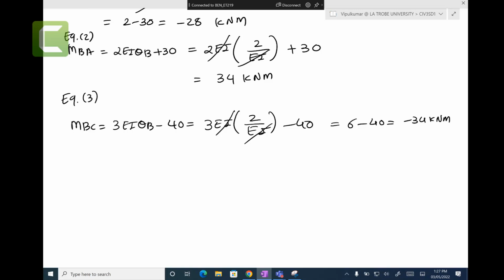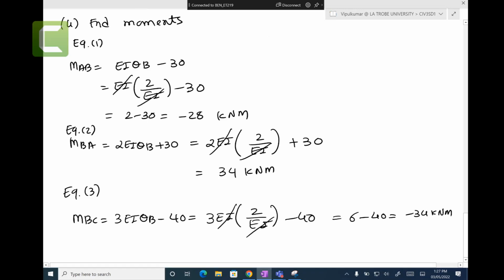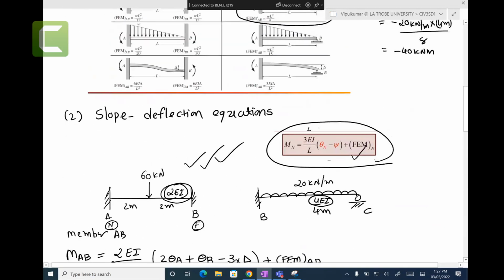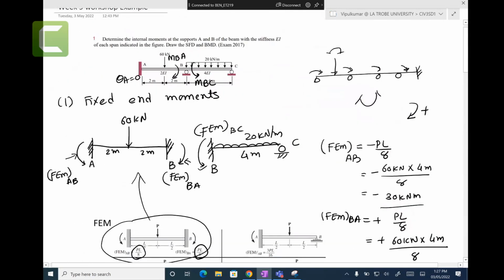Yes, please. Could you explain why we pick point B? For the equilibrium? Yes. In the lectures, in the force methods, we did static indeterminacy. Here we need to do the kinematic indeterminacy. Kinematic indeterminacy is called degrees of freedom.